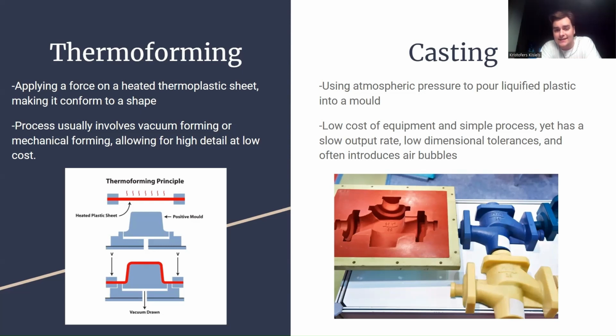Another method is casting, where usually a liquefied plastic is poured into a mold at standard atmospheric pressure. It is a low-cost process, but it has a pretty low output rate, pretty bad tolerances, and often involves a trapped air bubble, which can ruin the piece.